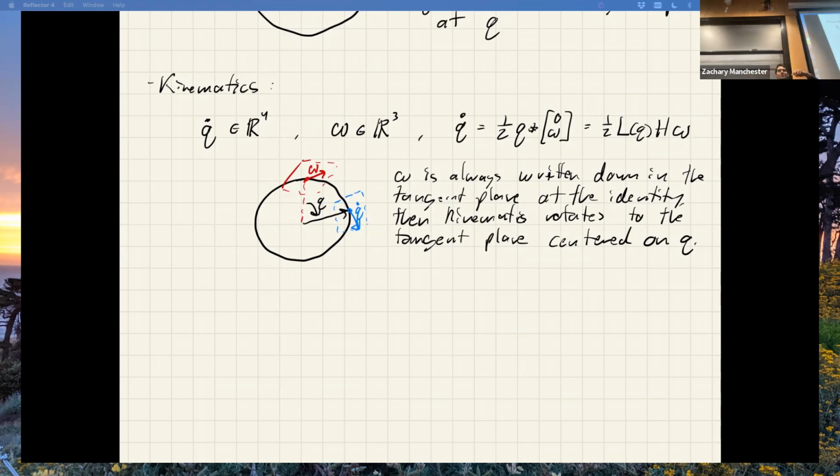So if I have latitude 90 degrees or whatever, I'm up at the pole. What's my longitude? Can you tell me the longitude at the North Pole? It's not defined, right? Because all the lines come together at the point. That's a singularity. So that's exactly what happens with Euler angles. When you get to a pitch equals 90, everything blows up because you're at the North Pole on this unit